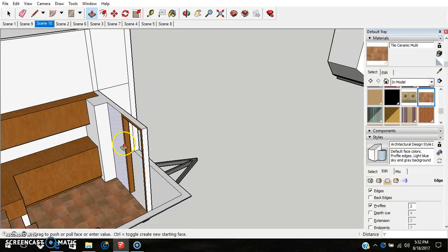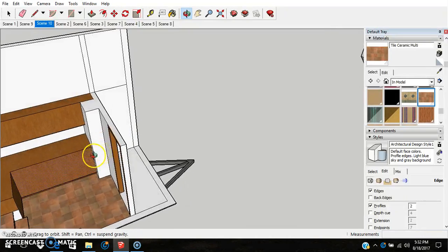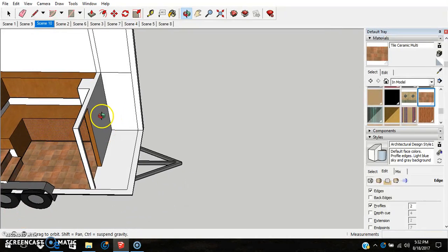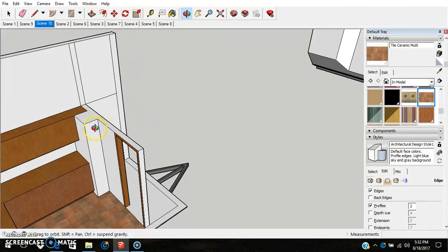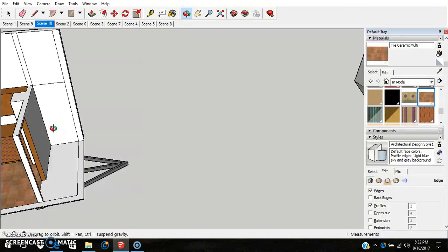And then on this other side, we'll just go over to the bathroom side. Actually, I might need a little bit more over here. So let's just measure that out. Let's say we want probably at least 30 inches. Can we get 30 inches for a shower here? Comma 30. All right. And then we'll add 6 inches here, just on the top. 6. Rectangle.